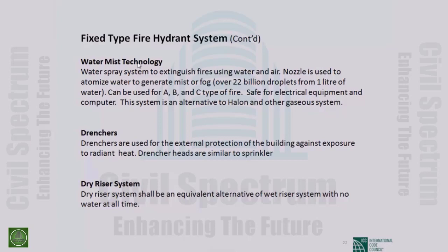So in addition to the A, you can use water. For the computer, you can use it. For the flammable liquid, you can use it, for all the electric system. This is a very, very effective system and very safe system because it is using non-toxic material, that is the water. Almost all gaseous halon, all other gas systems use those gases, those chemicals which are toxic. This is very dangerous. So if we can use water mist for our extinguishing system, that is always safe.